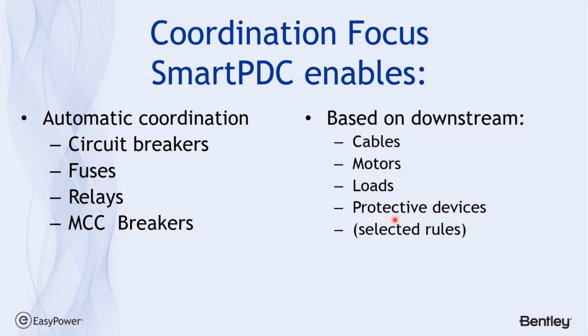Now, just a caveat here, the tool cannot adjust fuses because they're not an adjustable element, but it can verify that the fuse selected meets the rule requirements that are being given when the tool does the coordination task.